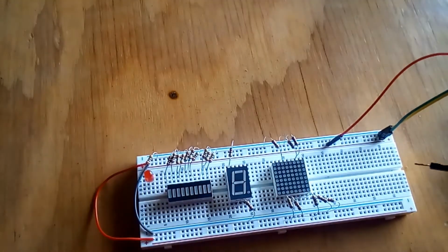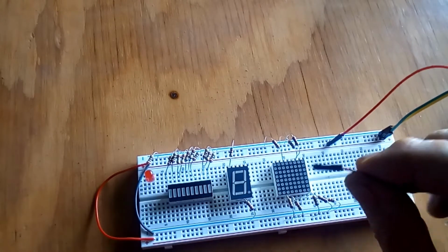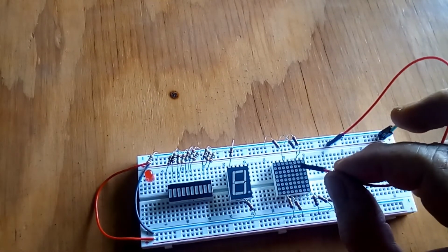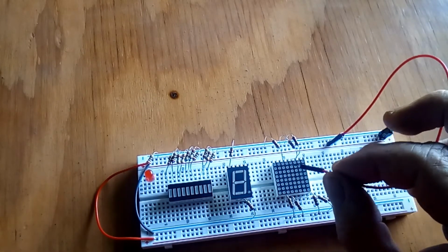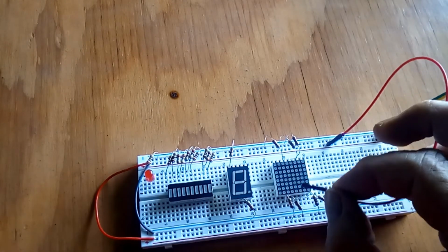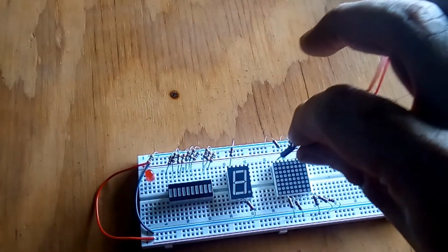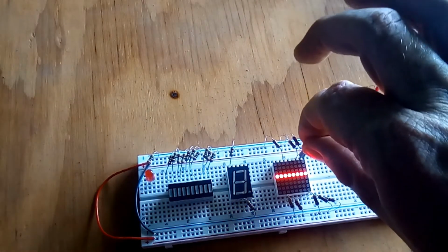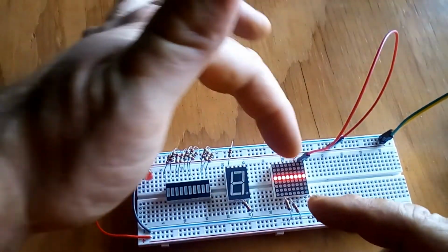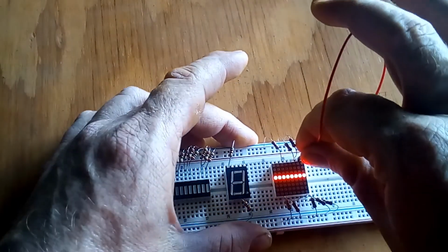So we can set up the multiplexing, and we have an 8x8 pattern of pixels basically. And that'll lead nicely into the next thing we're going to look at, because that's kind of like how we set up pixels on a screen. So it's an 8x8 array of LEDs that we can control any way we want just by multiplexing through some columns and rows. Turn on the LED for the row and column we want in the matrix, and then make any pattern we want show up on that.